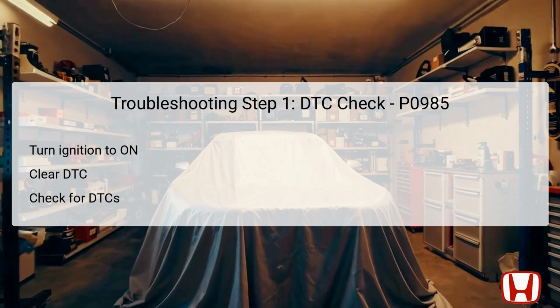This step is essential as it allows for the verification of any new or persistent issues that may appear after clearing. After clearing, start the engine and ensure the shift lever is in the Park P position. Then wait for at least 1 second to allow the system to stabilize. Finally, check for any pending or confirmed DTCs using the HDS. If DTC P0985 is indicated, this confirms that the failure has been replicated, and the troubleshooting should proceed to the next step.